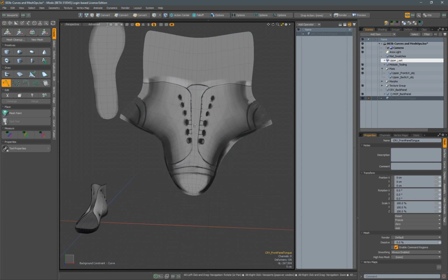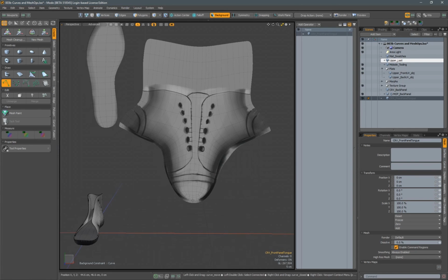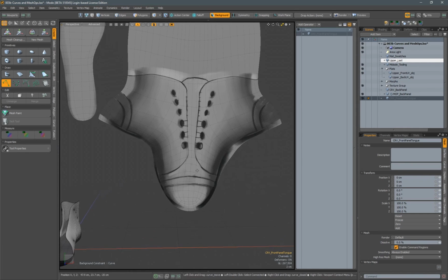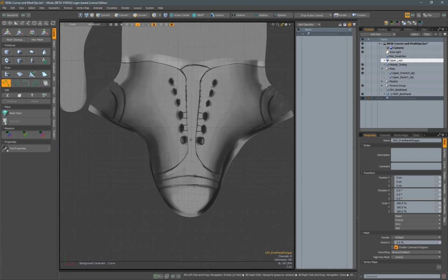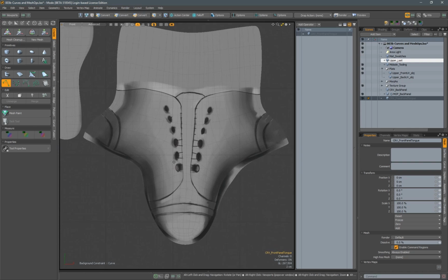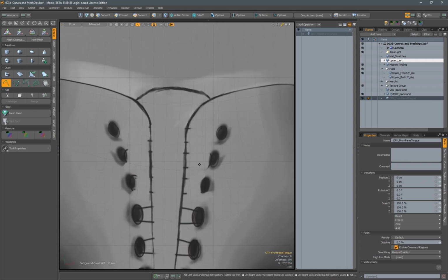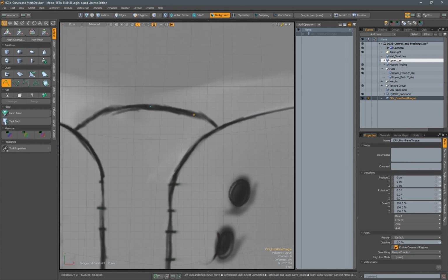Activate the spline curve tool. Make sure your mesh constraint is turned on so that way it snaps to that background item there, which happens to be the flat version. Okay, and I'm going to go to one of our orthographic views again, and that would be the front, and that's with numerical 2. And we'll go ahead and place in the tongue and front area here. So we'll start up here, and we'll go around this direction.